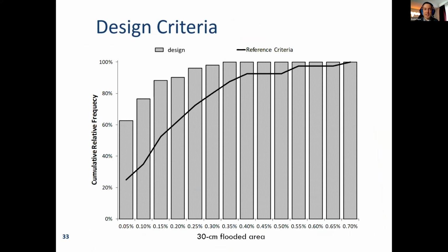The important thing to keep in mind is that prior to this project, there wasn't an accepted methodology for doing this kind of design, figuring out what an acceptable slope is. The state of practice at that point had been to go with a prescriptive final cover slope. So let's say 10%, say that's good enough. But the problem is there is a tension between what is good for drainage and what is good for erosion. So if you go to a steeper cap, you have more potential for erosion. And this particular final cover was meant to last hundreds of years.